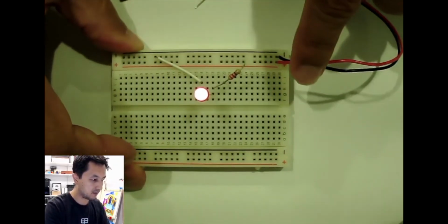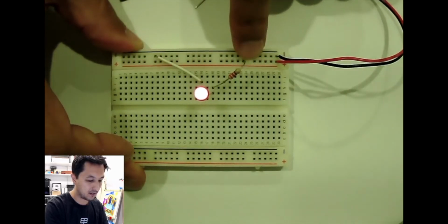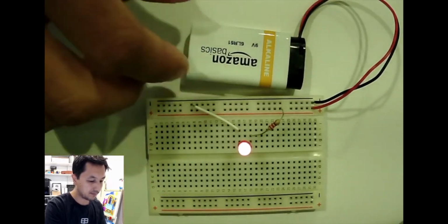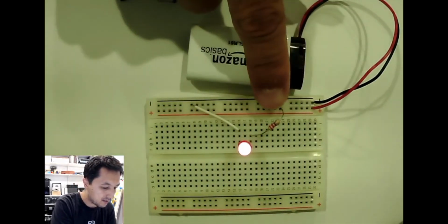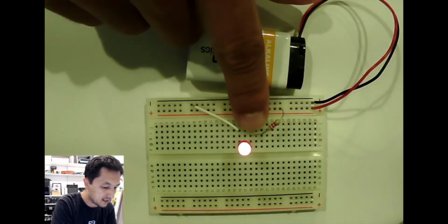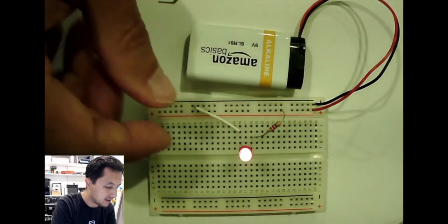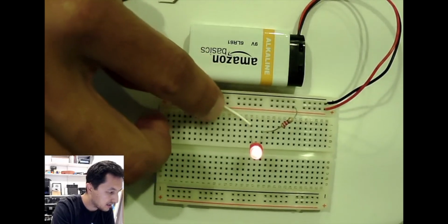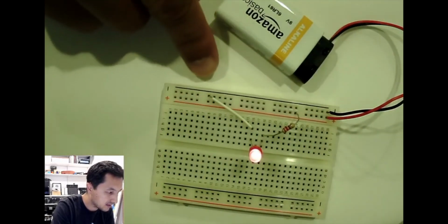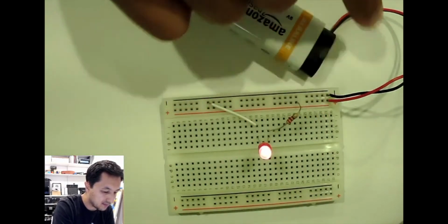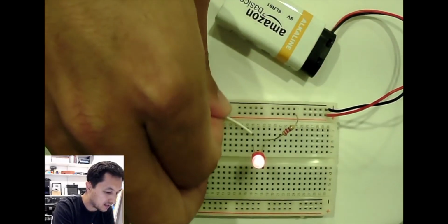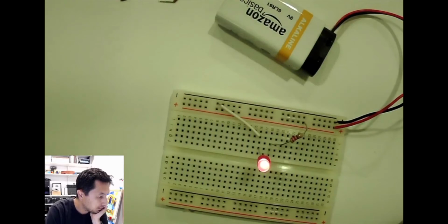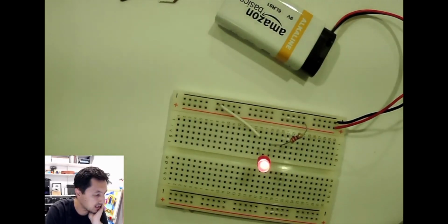So I have my power, the red cable running along this red power side, and then black is ground, which is connected to the battery. And then the power, the red part, is running through this 220 ohm resistor, which is then connected to the power side of the LED, which is the longer side. And then the shorter side is connected to this cable, which is then connected to the ground, which is the black rail here. So that's a completed circuit going back to the battery. If anything comes off, then the circuit's broken, and you have to reconnect it to turn it back on. That's basically what the circuit that I showed in the diagram is showing.